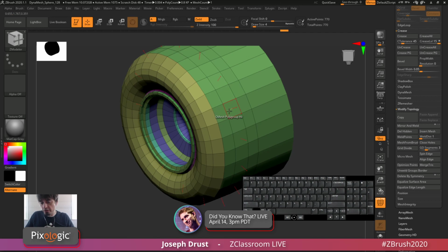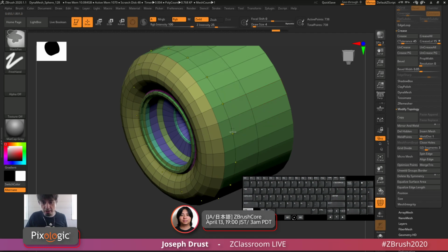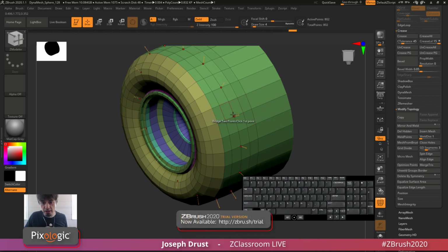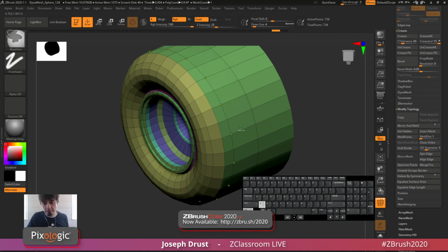So what you want to do is protect that edge first. If you want to create the hole on an edge, you want to make sure you add topology in the middle and in the edge, and then this is where you create your hole. If you're creating it on a poly, you'd want to add just the border protection around it. So those are the two options: on a poly, or, if I wanted to add it on an edge, I do it here.